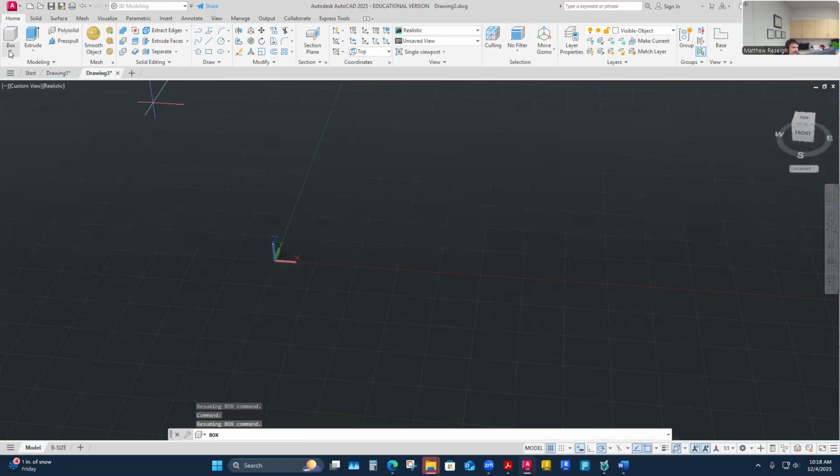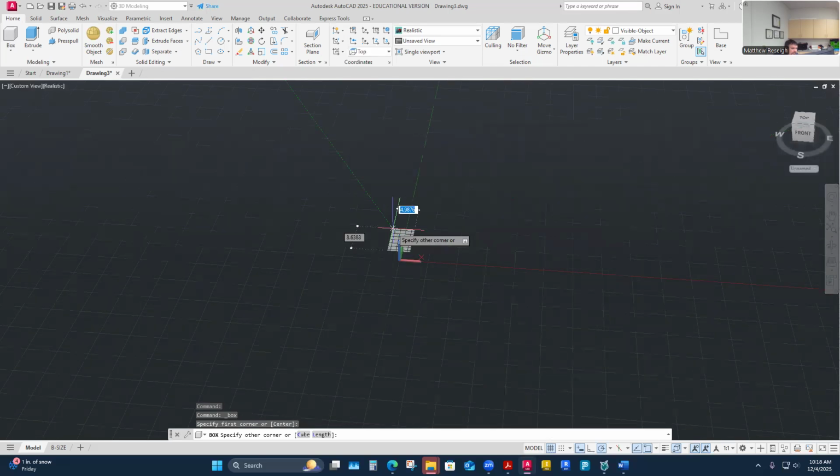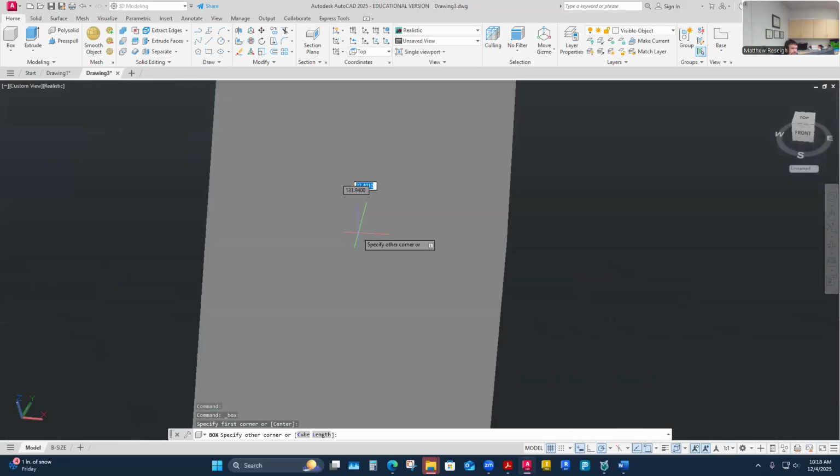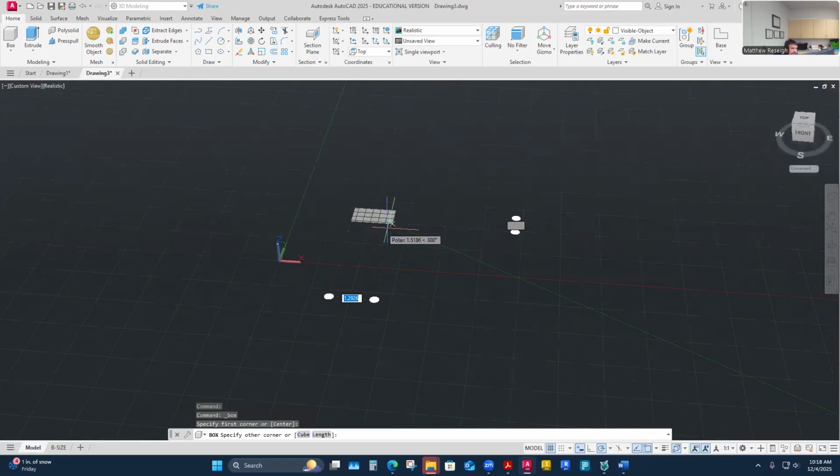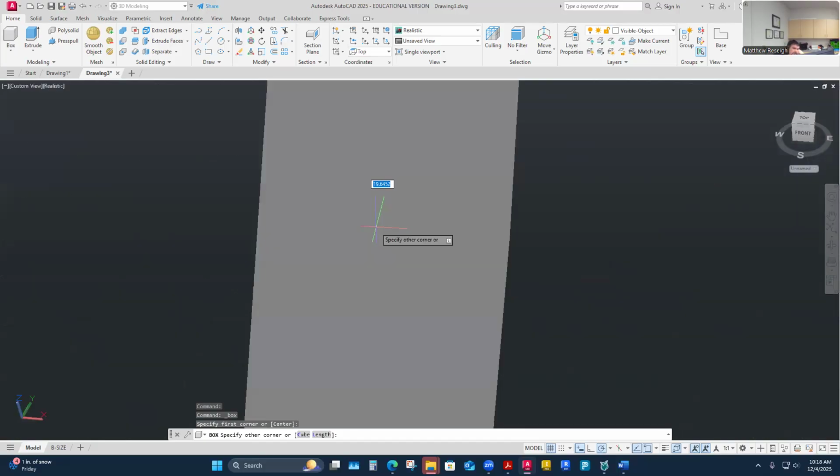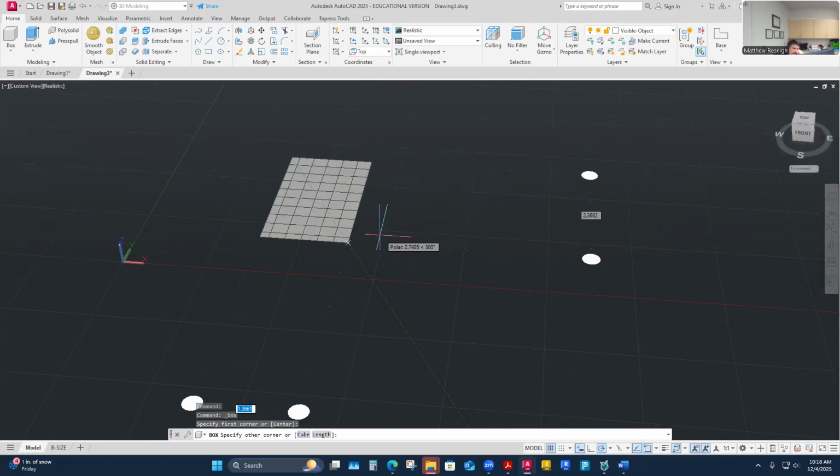So if you choose box and I'm on the top, it's going to ask, okay, what are the XY coordinates? I might just pick a place out here, like you would see me draw in the positive quadrant quite a bit. So I just left click. Now it's drawing a rectangle, because a box would start as a 2D rectangle. Let me zoom in here a little bit. I don't think I specifically put any dimensions that I'm going to draw.